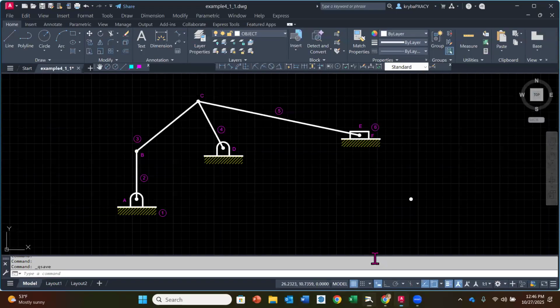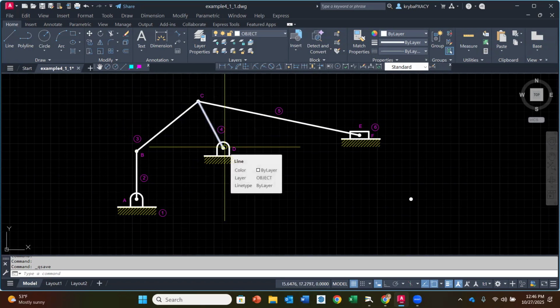When we look here at this mechanism, if you recall, when we drew the circle for the radius of link number 3, it connected with the radius of link number 4 in 2 places. All right. So there's 2 actually different places that those could connect at the position that this is at. So that means that those links need some extra help, like to know where they are. So they're going to be needing some help positioning themselves. So we have 3 of those.